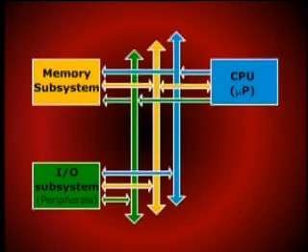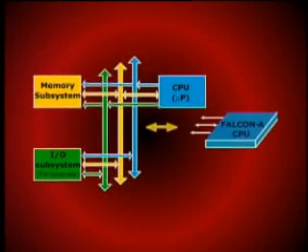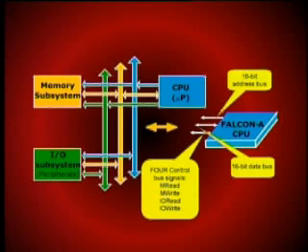The slide just symbolically shows what you already know. Let us say Falcon is available in the form of a chip, and we have an external interface in the form of a 16-bit address bus, a 16-bit data bus, and some control signals available on the control bus. The control bus could include signals like memory read, memory write, IO read, IO write. If you see a similar figure for SRC, then the widths of the address, data bus, and control bus would be different, and in that case it would be only memory read and write because IO would be memory mapped.